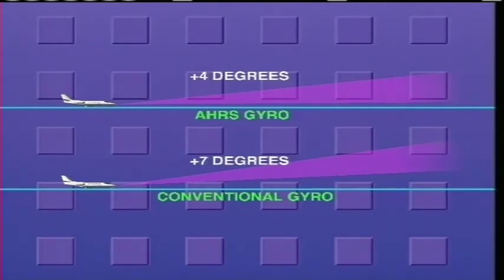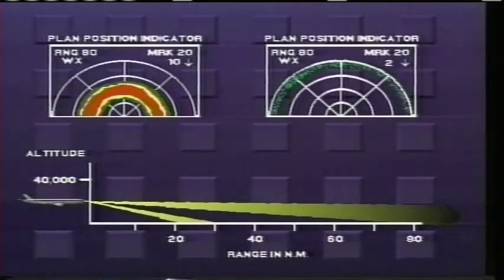As a rule of thumb, on climb out, pilots should reduce the initial tilt setting by approximately 1 degree for each 10,000 feet of climb, or until ground returns appear on the outer edges of the scope. Once the ground returns are presented on the outer edge, small adjustments to the tilt can be made to maintain that presentation.